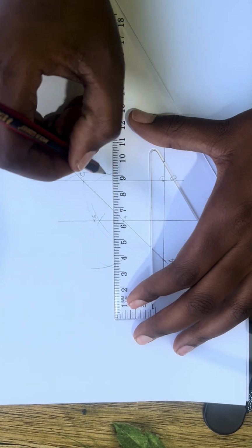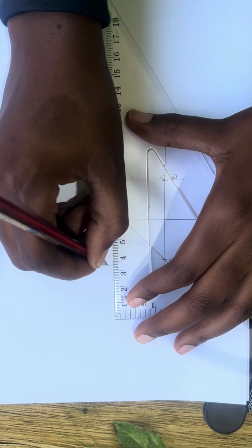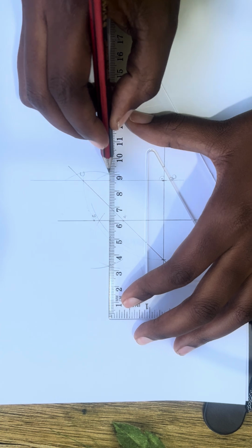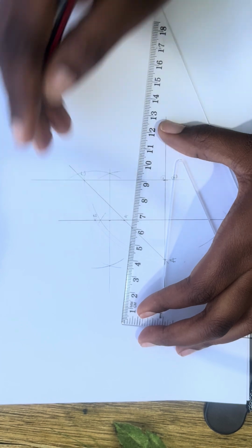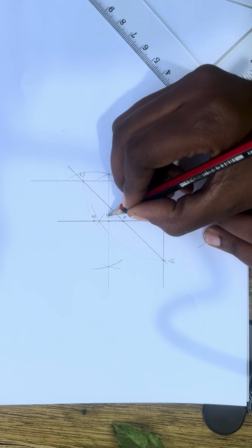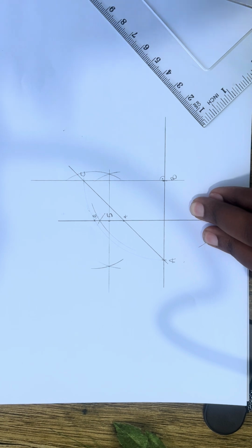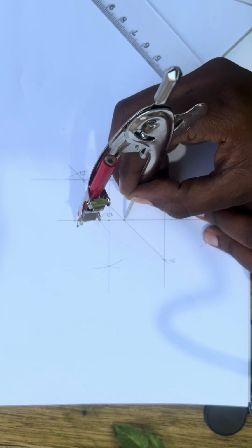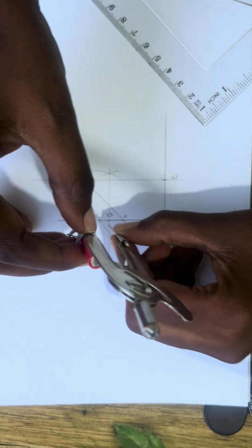I think this method is now not hard since we looked at it earlier, almost in every lecture, the perpendicular bisector. So the point where this perpendicular bisector divides the line 6, 4 is 5, which will be used for drawing our pentagon. So you pick the distance between 4 and 5, or 6 and 5. Pick that distance.